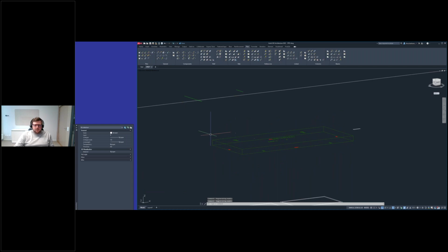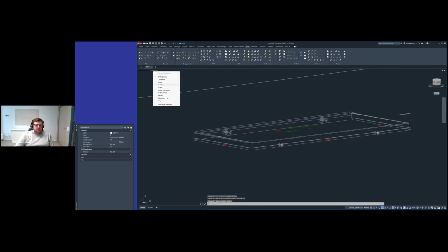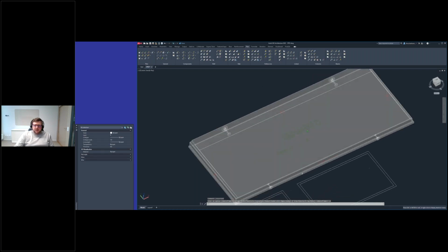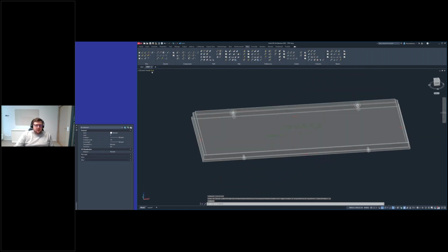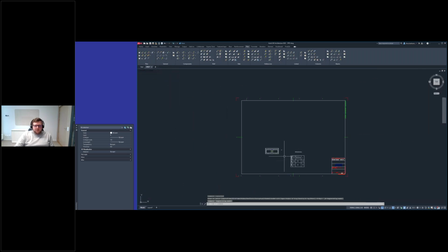And as we know, we only see the end caps in solid mode, so I can switch to solid now. And now we can actually see the end caps. I can switch it to X-ray to see it a little bit clearer. So this is great, but to make it easy to work, I will go back to wireframe.